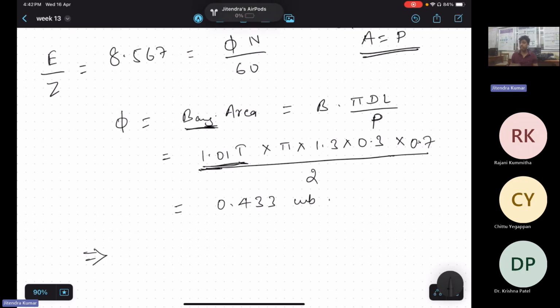Yeah, you are correct. We are calculating here the flux in the air gap. Why? Because whatever flux is there in the air gap, it is only that which tends to cross and again enter the cores. So that is why we are concerned with the air gap flux density. Corresponding to the air gap flux density, how much area are you considering to make that flux linkage, right?